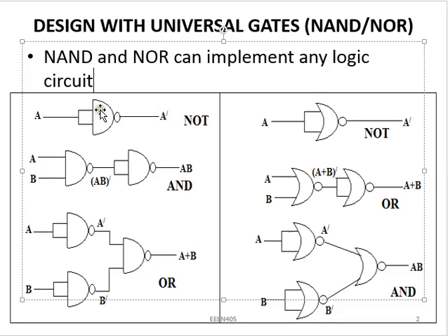All we need to do is to use 2 input NAND gates, connect the 2 inputs and deliver a signal which is A. At the output you have A prime, which is exactly the operation of an inverter, NOT gate.